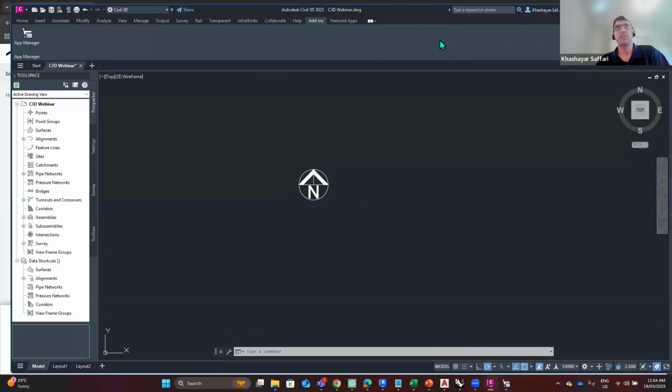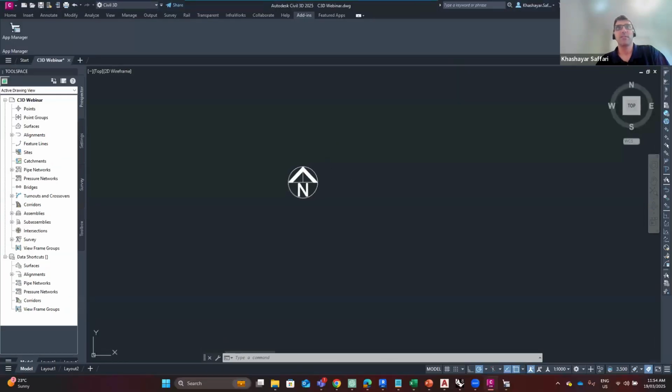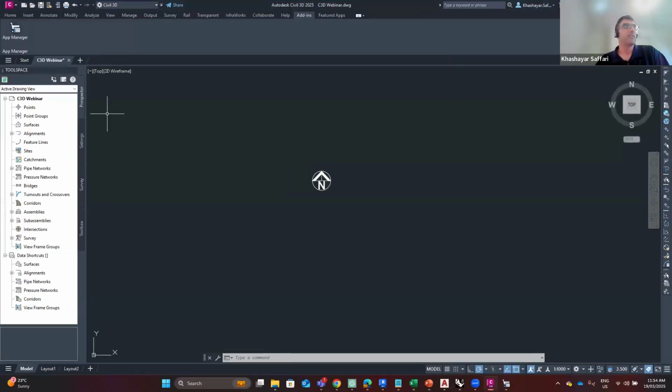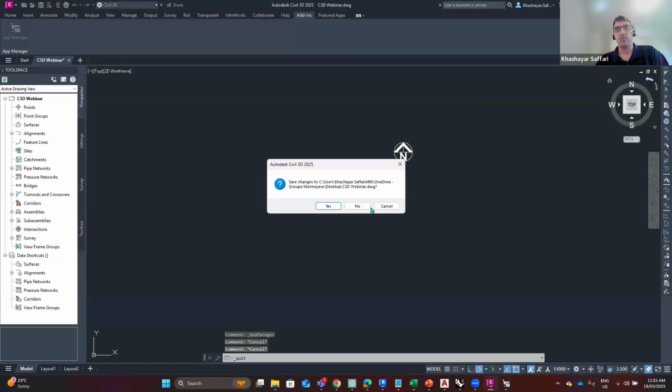I have many software open, that's why it doesn't come up, but it's exactly like AutoCAD. It will show all the add-ins and then you can see UNIFI is installed. And then that's good to go to use Content Catalog.